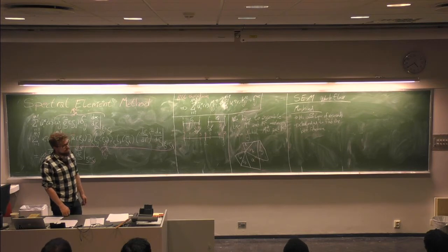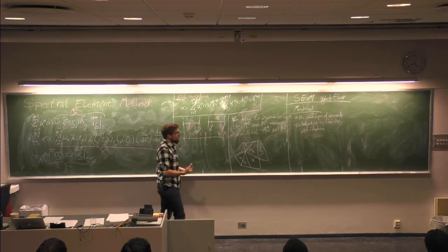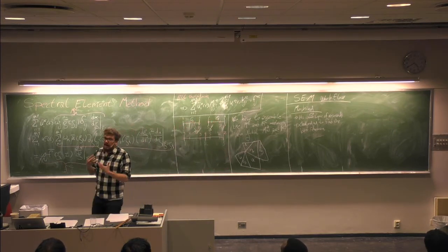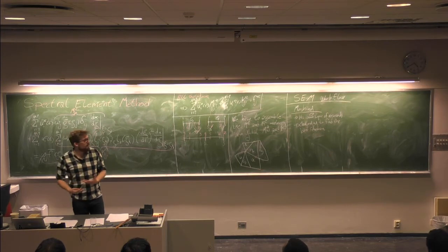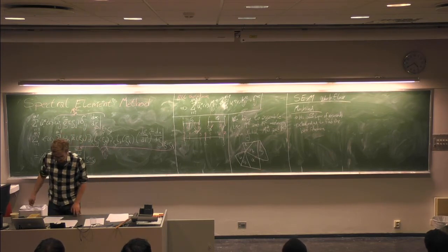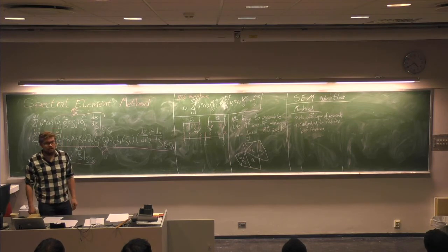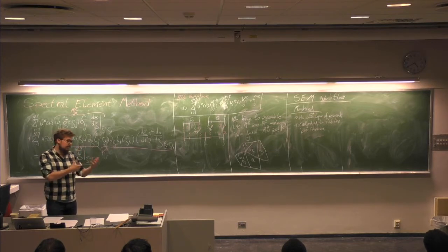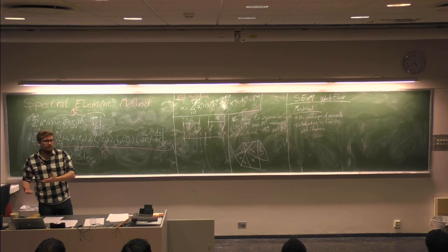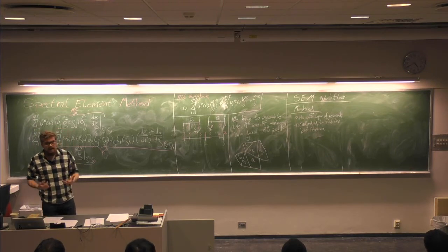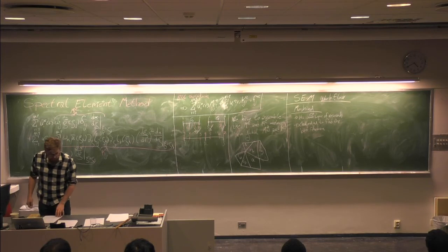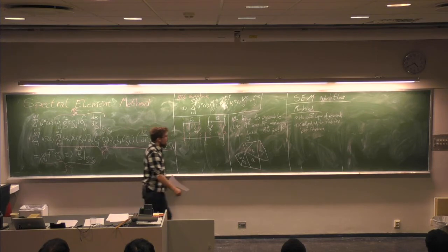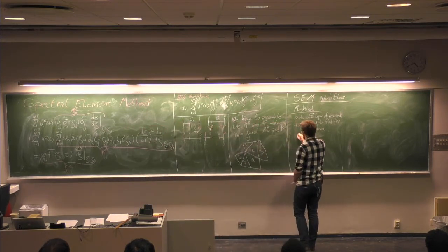I mean, you can do it in a brute force method and just have a very, very fine mesh, but then your result is going to be accurate, but it's also going to take forever. So then you have to find a middle point. You have to have a coarse enough grid that you actually have time enough to do the computations, but it also has to be fine enough in order for you to get accurate results and not end up destroying equipment for millions and millions. And if you're to do this, there is specialized software to actually create the meshing.